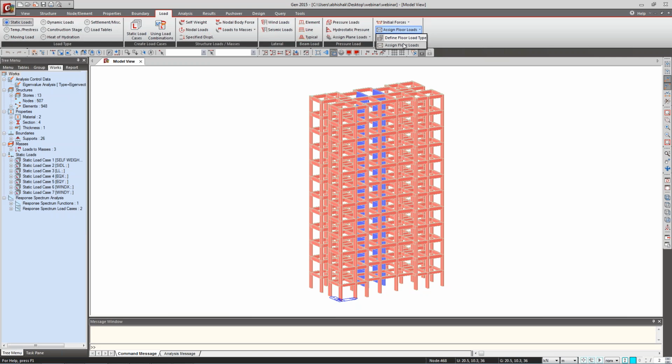At the time of the modeling, if you are facing some problems, sometimes in the bottom it's showing that the load is not transferred, or some cantilever portions are there. So these are some errors coming in the message window. So what is that identification? That means somewhere your joint is wrong.